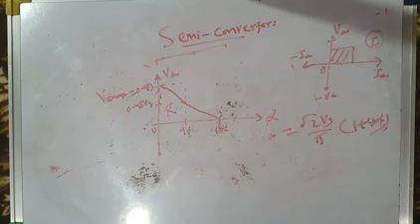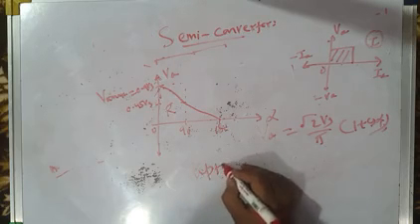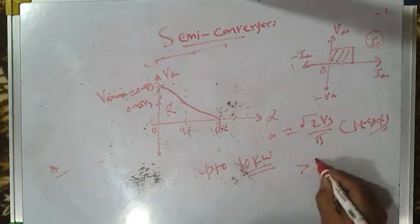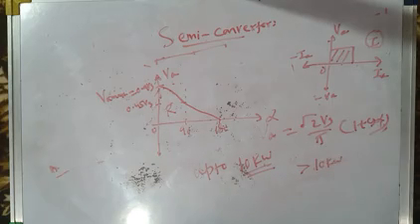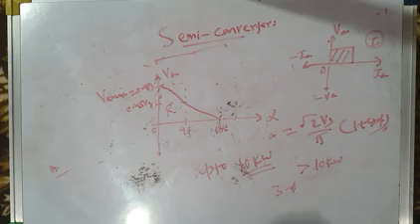So this was a general overview of a DC motor drive, how a DC motor drive can be supplied by converters. I started with simple half wave converter. For low voltage, low power ratings, you can use a half wave converter. And for ratings up to 10 kilowatts, you can use single phase converter fed drives. And for greater than 10 kilowatts, up to thousands of kilowatts, you have to use 3-phase converter fed drives. Okay, up to 10 kilowatts, single phase converter fed drives.